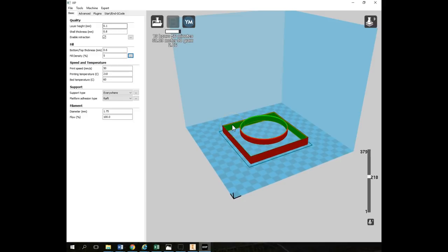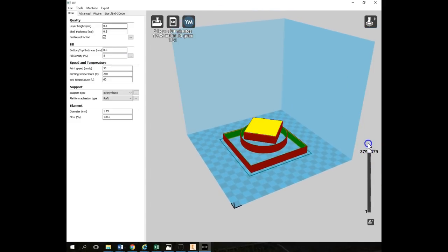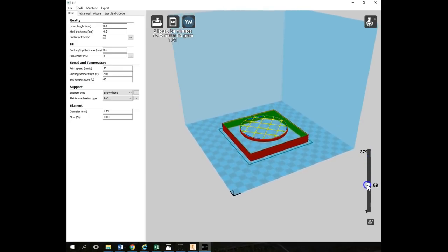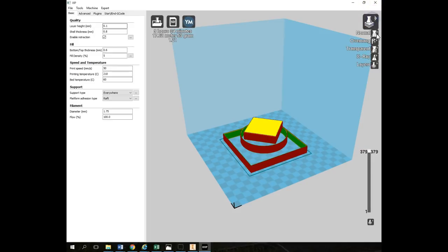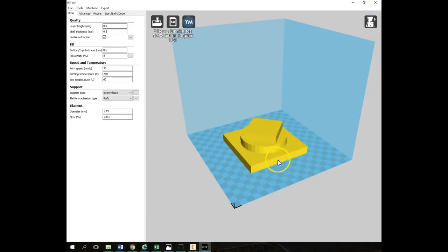If you take this down to a 5% fill density, what you're going to notice is that you can press down on the top of that thing and it's going to give a little bit because there's so much space in between there. And this object is going to be easier to rotate and shear, where you turn this in one direction and this in the other direction, and it'll turn itself off. So yeah, you need to figure out what's best for your object according to the stresses that it's going to be placed under. Now, back to normal for a second.